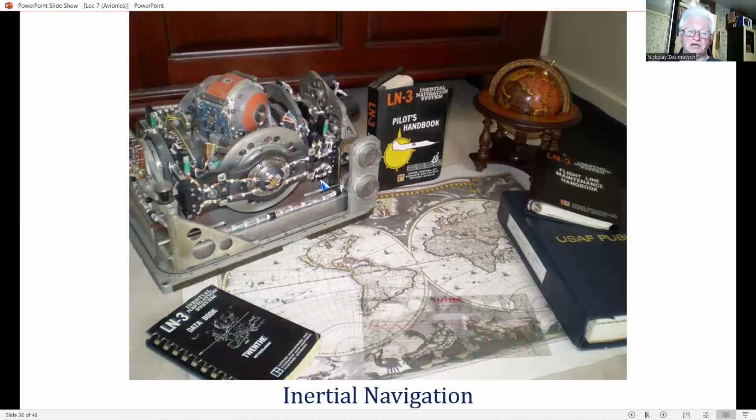The gyros used in all the designs of control and guidance systems are what is termed spinning rotor gyros, as they exploit the angular momentum of a spinning rotor to sense angular motion. However, their mechanical complexity and inherent failure modes constrain their cost and reliability, and hence cost of ownership. Power consumption and run-up time are further limiting parameters of this technology.